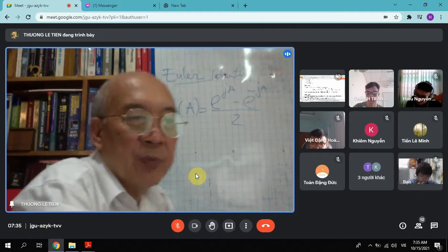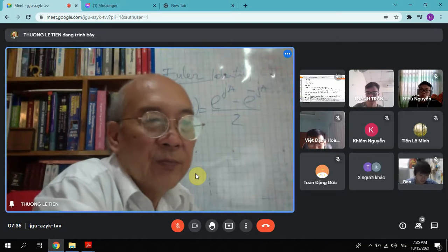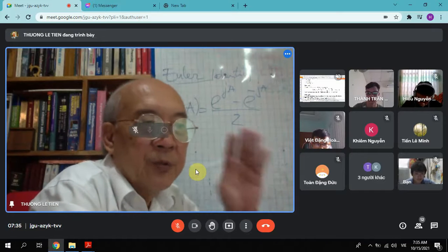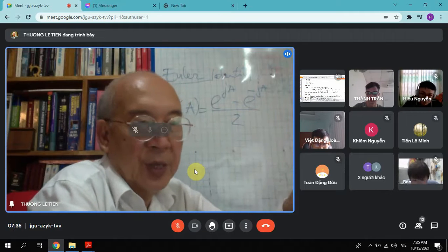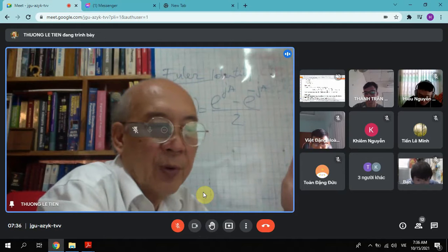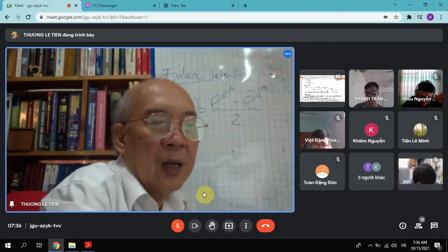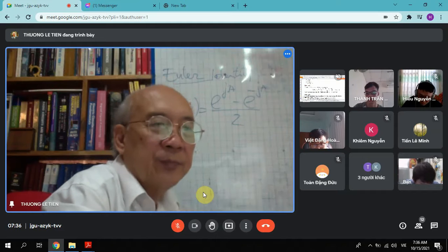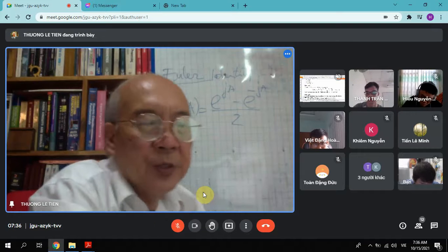At the end of chapter 4, we already talked about the eigenfunction or eigenvalues of the system. That means it's straightforward. Some students answered: the first step, convert the s[n] into the frequency domain by using the Fourier transform, and after that, taking the multiplication of H(omega) and S(omega). Finally, take the inverse Fourier transform to get the s[n]. That one is correct also, but it takes a long way to go.